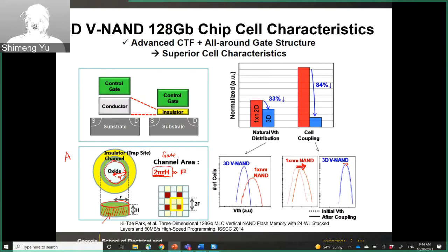And in the two-dimensional NAND flash we discussed before, it's just F squared, right? One cell is 4F squared, but actually the gate area is F by F in the 2D case, in the two-dimensional space. So for those parameters, for example, the radius is much larger. As we discussed before, we relax the lateral dimensions in the 3D NAND flash. And the radius can be like 60 nanometer or even 80 nanometer, and the height can be like 30 nanometer. So you can calculate that.